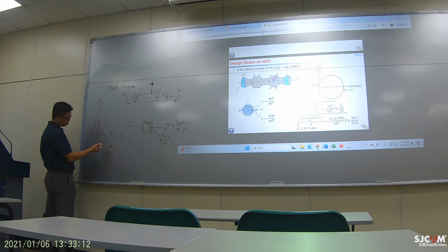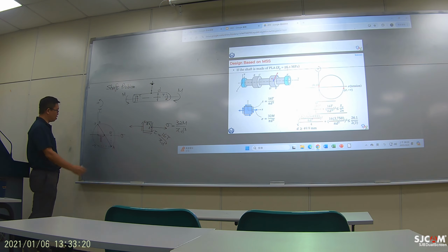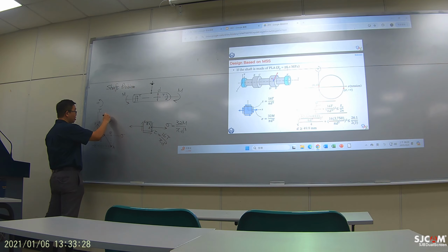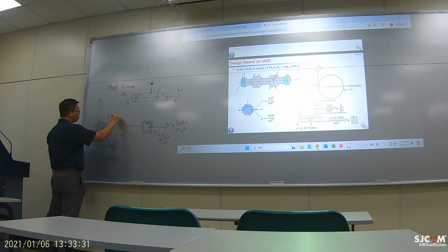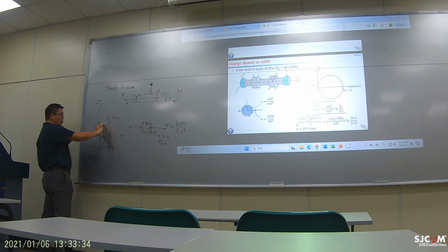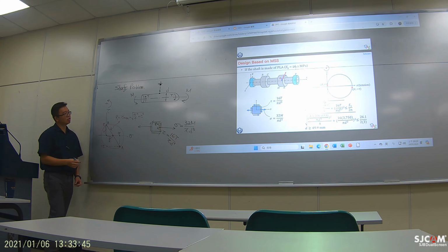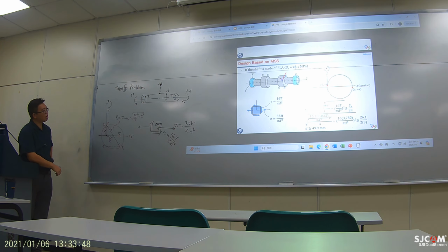And right here you can see this is half of your stress, and this is tau. So the radius right here, the radius equals tau max, of course, because this is where you have the maximum shear stress, would be the square root of sigma squared over 4 plus tau squared.